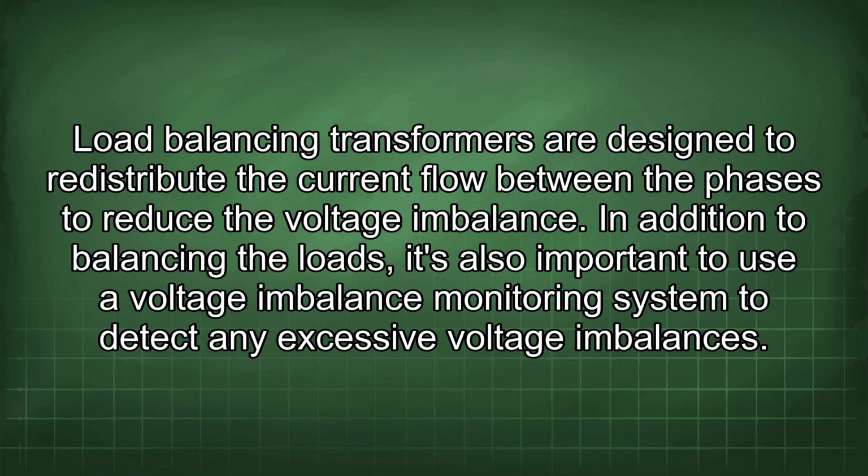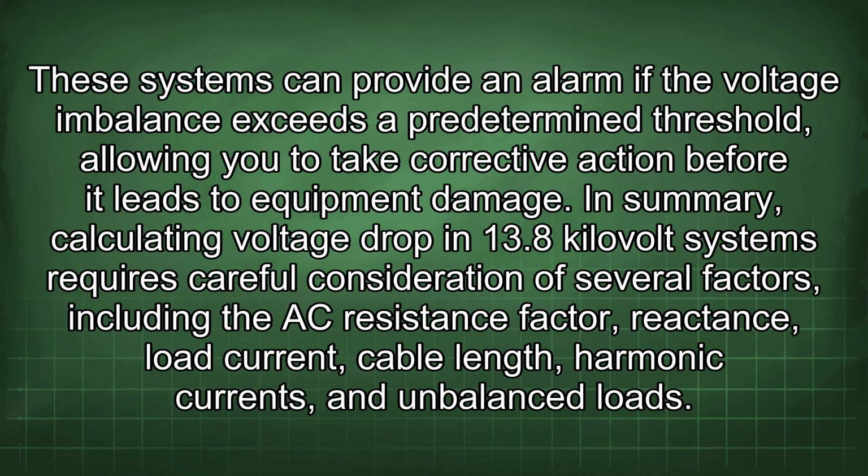In addition to balancing the loads, it's also important to use a voltage imbalance monitoring system to detect any excessive voltage imbalances. These systems can provide an alarm if the voltage imbalance exceeds a predetermined threshold, allowing you to take corrective action before it leads to equipment damage.